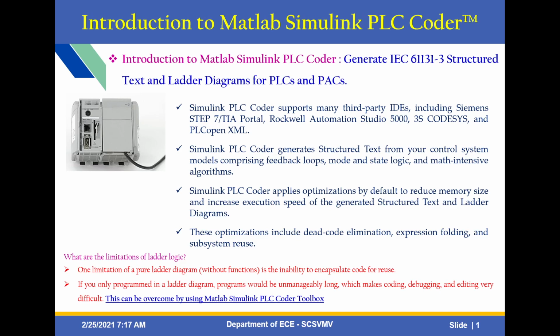Here, the 5 programming languages that are defined in the IEC 61131 standard: the first one is the ladder diagram, better known as ladder logic, then function block diagram FBD, then sequential function chart, that is SFC, then instruction list IL, and structured text ST. SFC is used for pictorial representation of a system's operation.